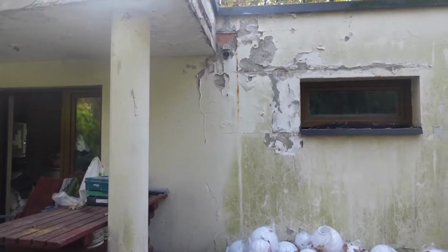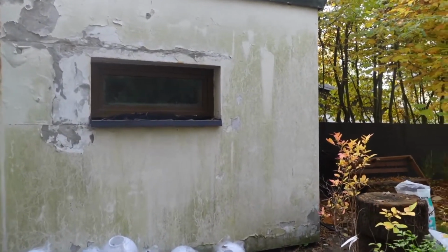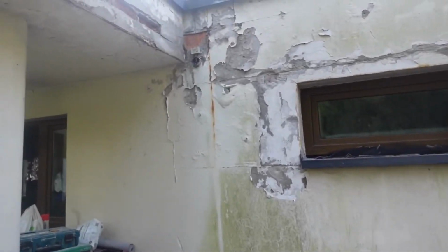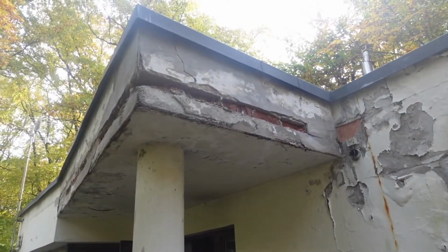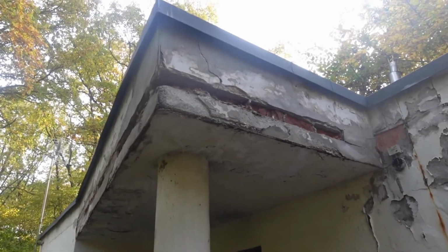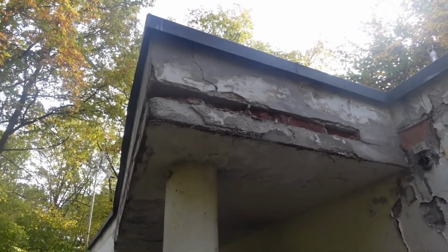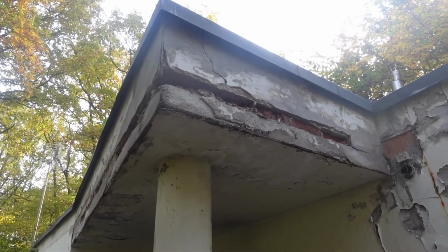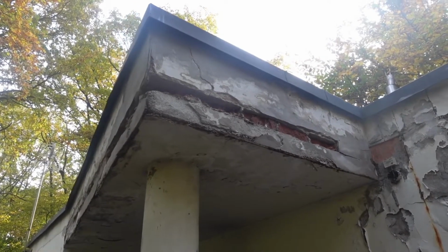I'd like to draw your attention to the damage caused by moisture and biological contamination. This building looks very representative of how, as I told you, the house on this property looked. Due to lack of heating, roof leaks, damage to the metalwork, water began to seep through the ceiling, simultaneously affecting vertical barriers, which caused the destruction and cracking of the plaster. You know, temperature changes. In winter, this phenomenon is particularly intensified. Water expands, all structures crack.